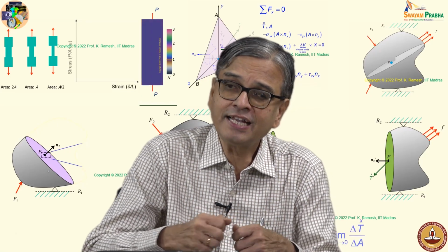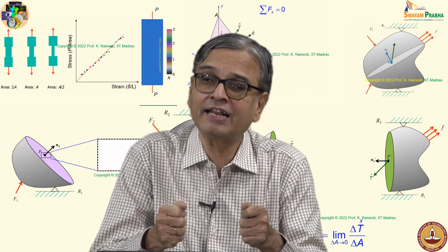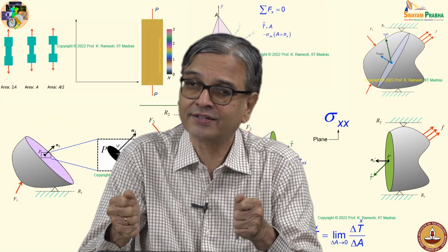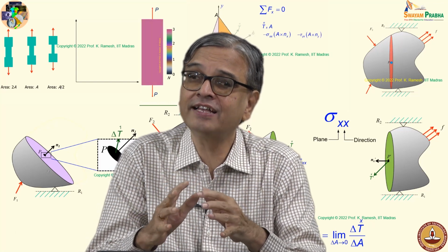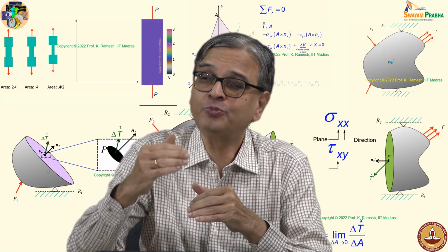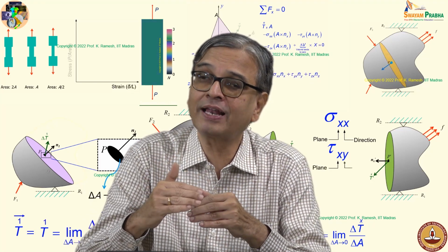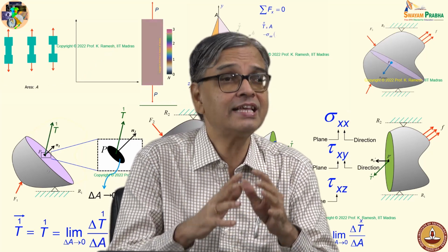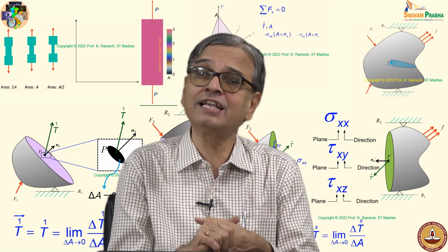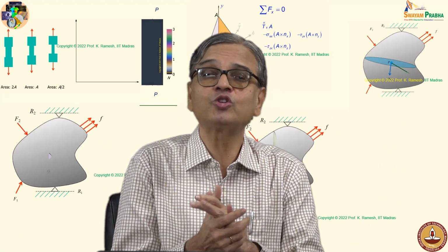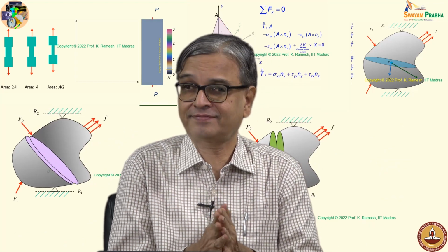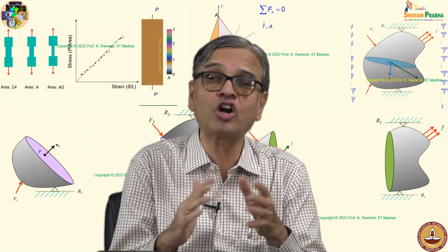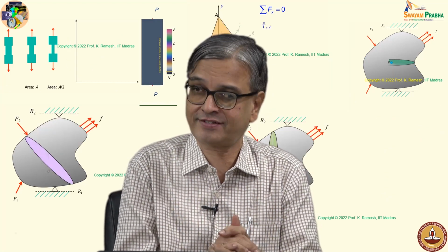And as I go nearer and nearer that I apply a uniform loading, fine. What I find is the fringe pattern becomes of uniform color earlier than the previous case. And this is embedded in a nice principle which goes with the name Saint Venant. Okay. In fact, he developed this concept in the context of bending stress.